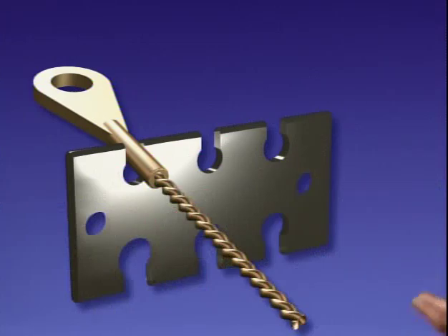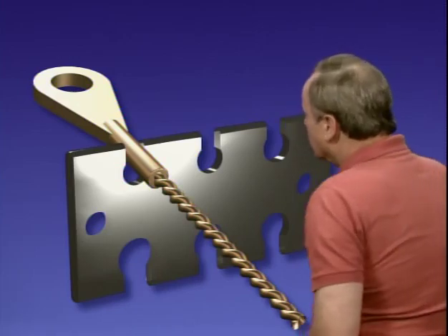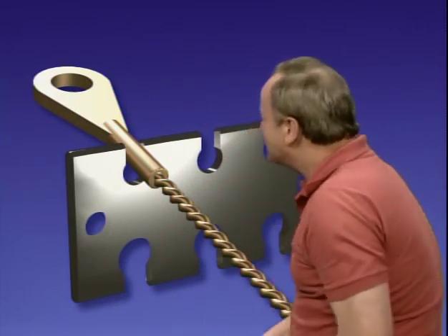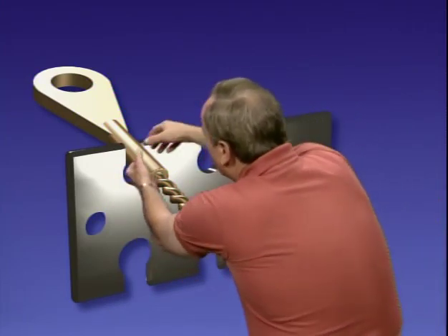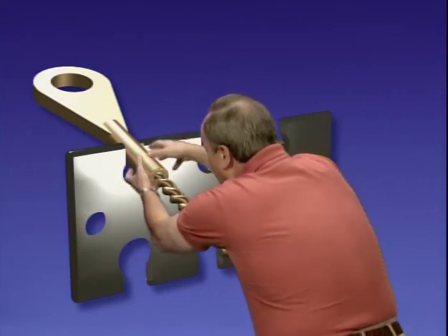fittings. Now, let's assume that you've just inspected an aircraft, and one of the things that you have decided is that you need to replace the control cables. Well, when you do that, one of the things you'll also need to do is reattach a terminal to a cable. Now, how are you going to do that? Well, these days, the way you do it is press it on, or what they call swaging it on. This is called a swaged terminal.